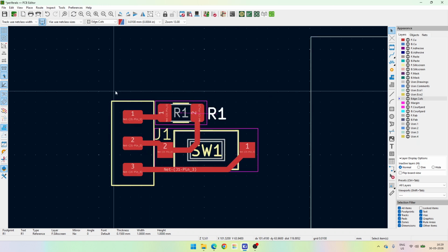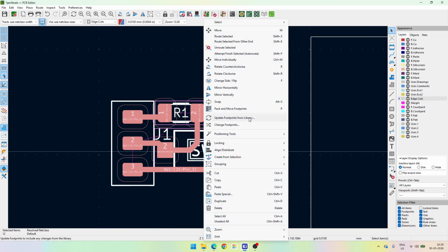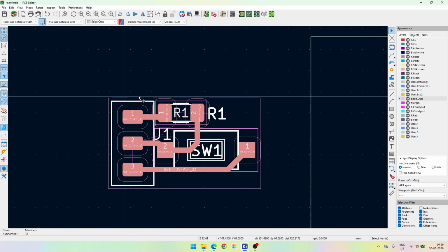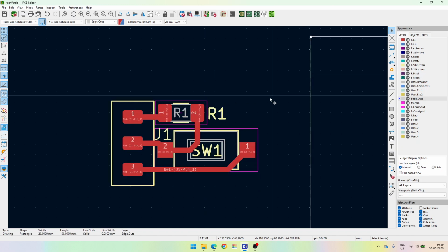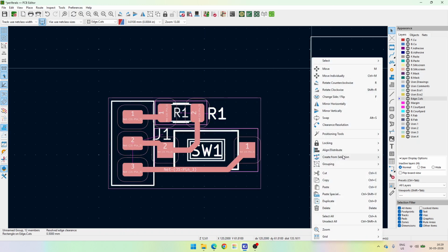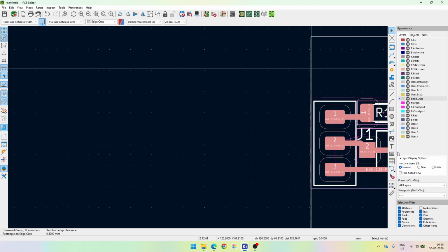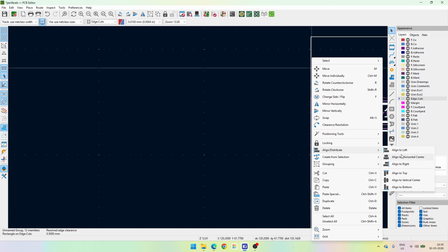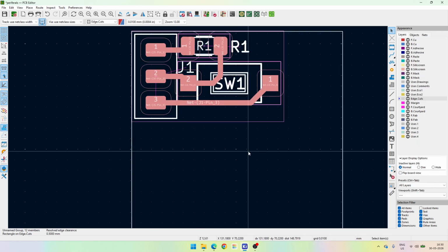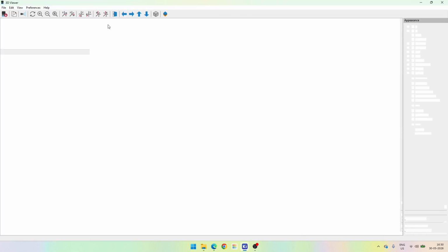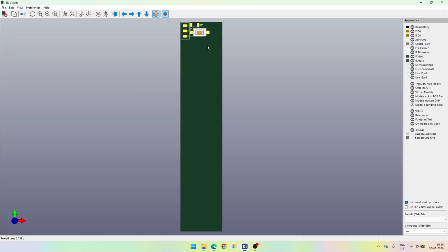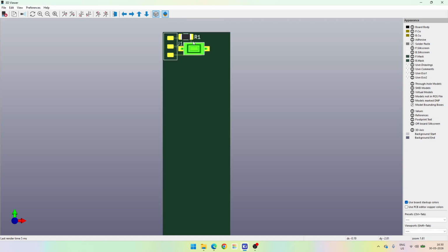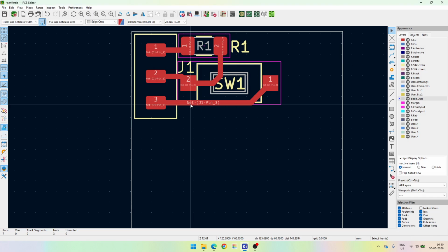So once that is done, what I can do is I can simply organize this again. See, what I am trying to do is if I draw a box, whatever I have placed and whatever pins I am trying to place should all be covered within that particular box. That is because once I group this, it draws a box around it, and then I'll select both of them and distribute to the left and align to the top. So if you see now, this sits on the top edge of the board, right? And I have clear visibility as to what I can put around it.